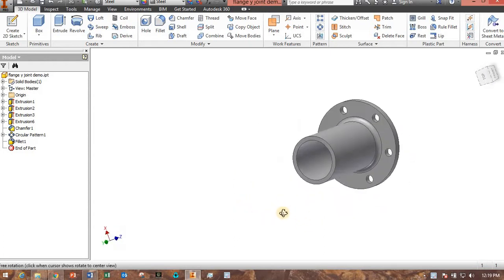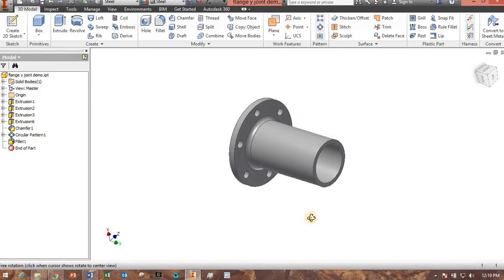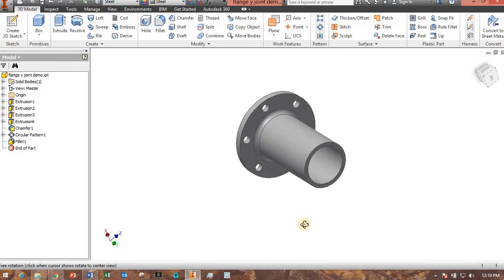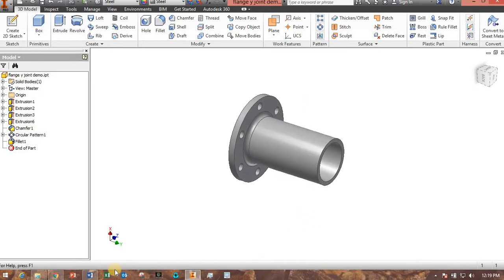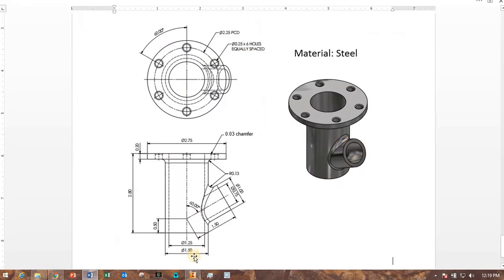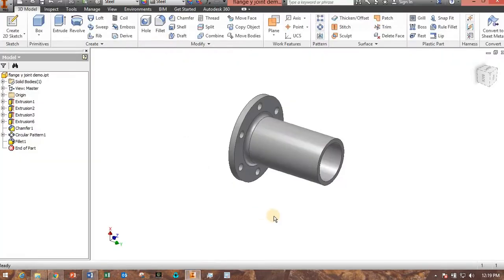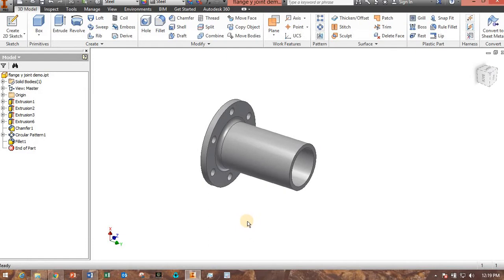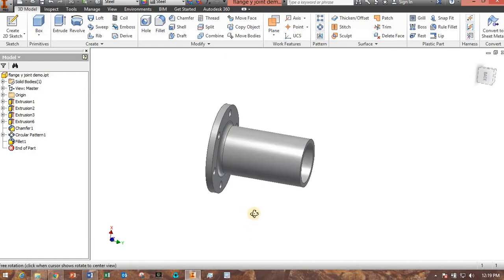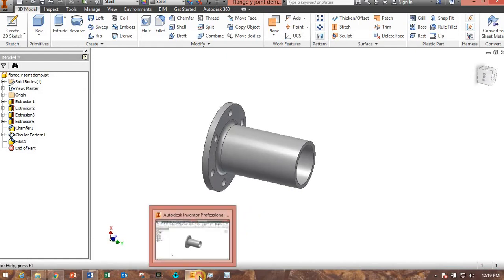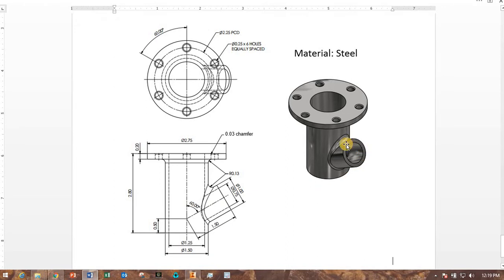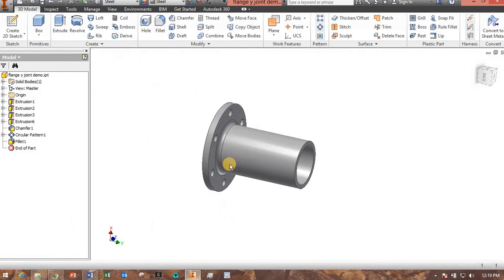So here's basically the simple foundation. Let me not show all the details, but just briefly show how you would add in that Y junction here. Okay, so the Y junction we're going to do with an extrusion. But when we make the extrusion, we need a plane that is at an angle here so that I can extrude down in this direction. Okay, so here's how we can make that plane.